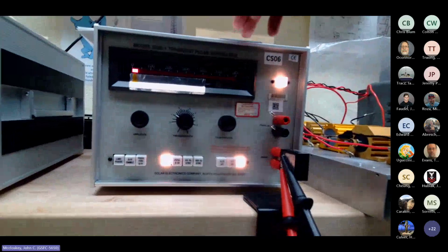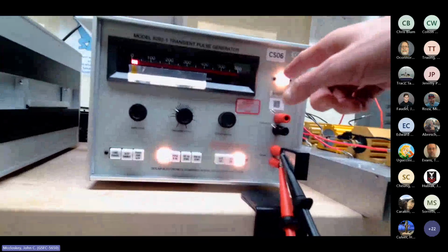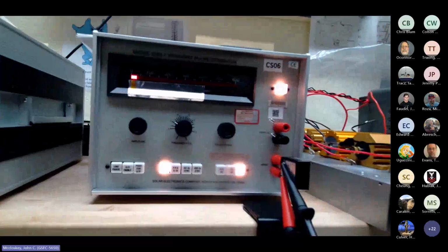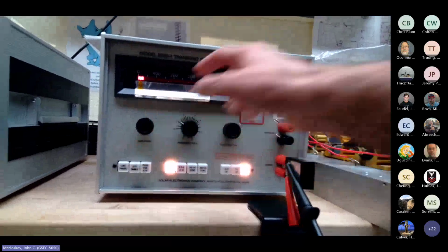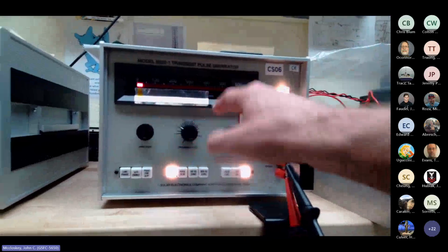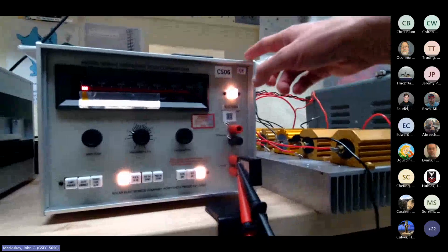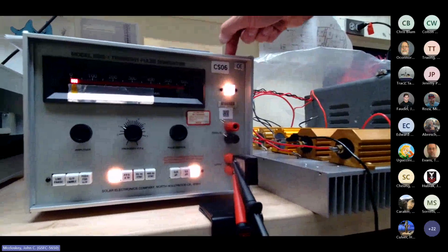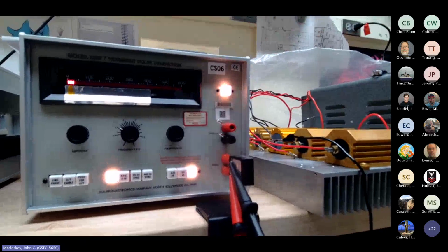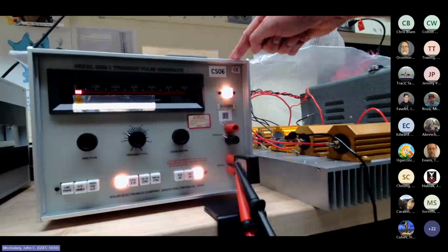So with this thing not having an enable switch, ideally you just want to turn it off without touching the volume. That's the guitar player in me talking. The amplitude knob, it would be ideal if you just switch this off, don't touch anything, hook it up to the EUT and turn it back on. But for the same reason as with CS101, you want to turn on your drive circuit, your drive equipment, before you turn on the EUT. You want to do that here too, if you're doing the series injection method.